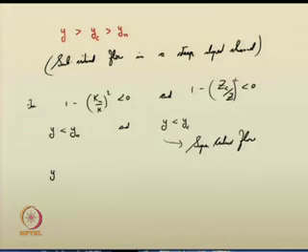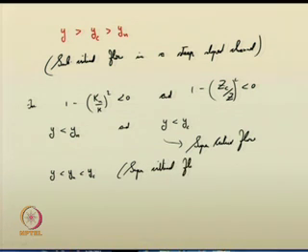So, for example, if y less than y n less than y c, this implies supercritical flow in a steep slope channel.